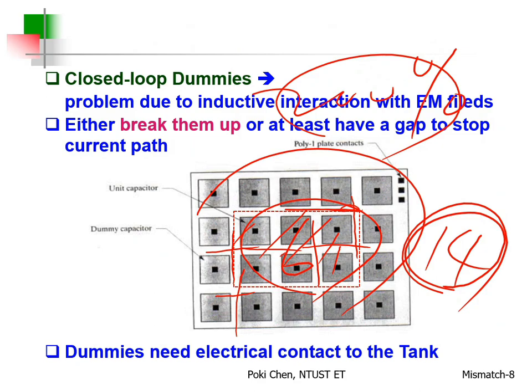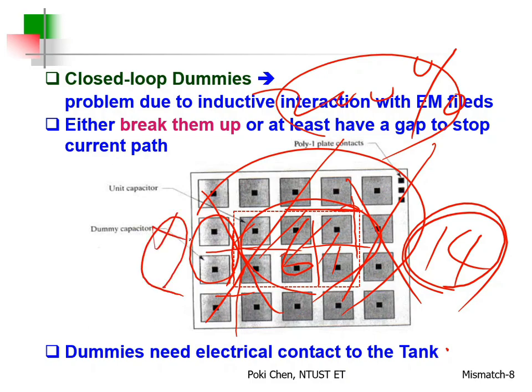Usually, we wouldn't like to have this, especially for resistors, capacitors. All right? But how about transistors? Sometimes you need. Okay? Sometimes you not only need to use the same transistors for dummy, but also you need to apply double dummy. Oh, what does it mean? Not only one dummy, but two dummies. Okay, with the same size. Got it? For what?